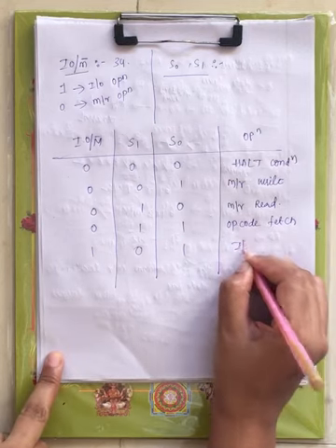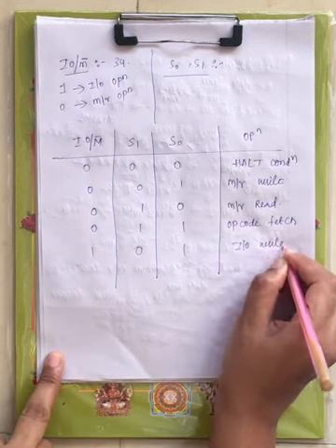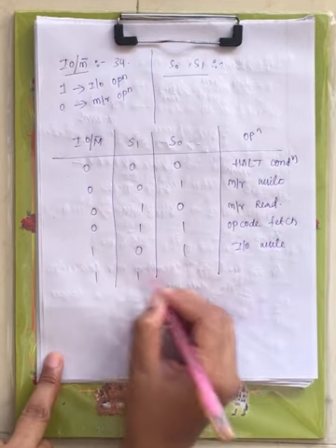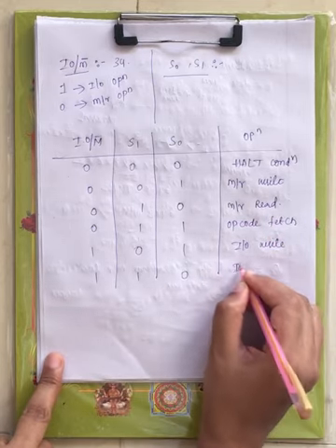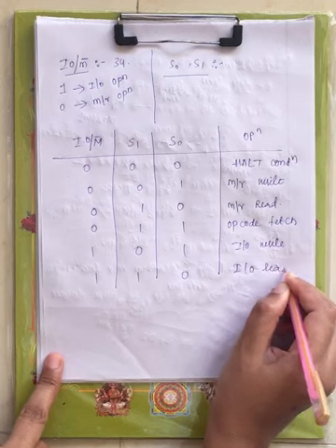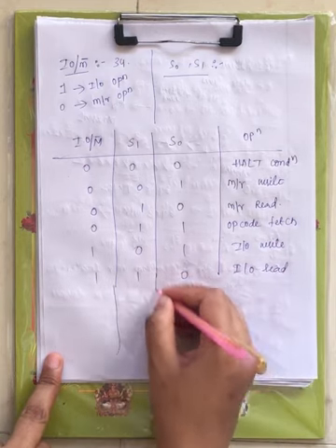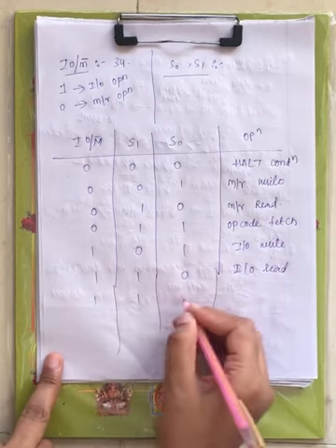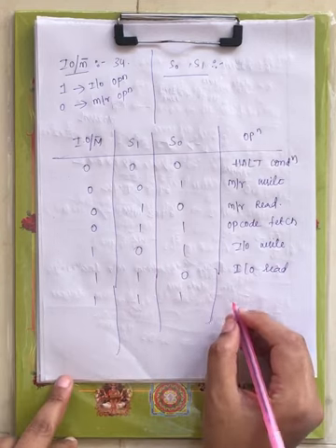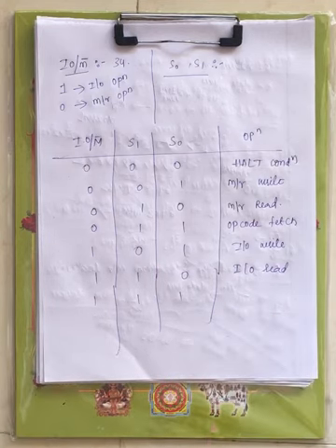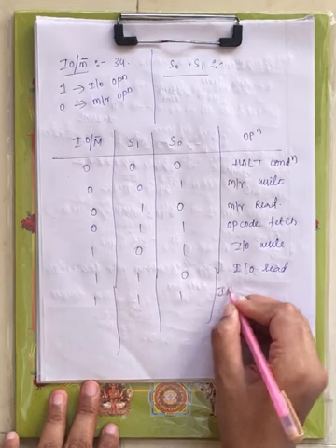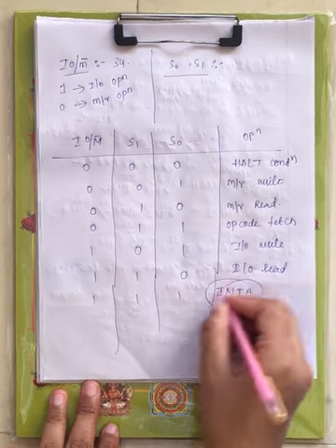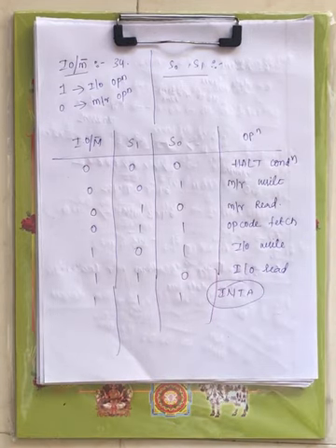Now here you will get input or output write operation. When it is 1 1 0, that is IO read operation. Now what is left out? All ones, that is the interrupt acknowledgement signal. Now what is interrupt acknowledgement signal? We will see later.